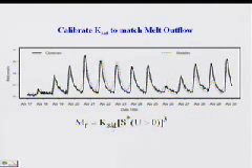And then there's this melt outflow parametrization that says the melt outflow is proportional to a saturated conductivity parameter and relative saturation. We adjusted this parameter so that you could get the diurnal pulses of melt outflow matched between the model and observations. The melt outflow doesn't really play much of a role in the overall melt energy balance. Once water's melted, it's going to pour out the bottom of the snow sometime, so this diurnal pulsing is just really how rapidly the snow drains.